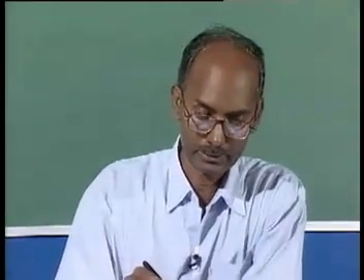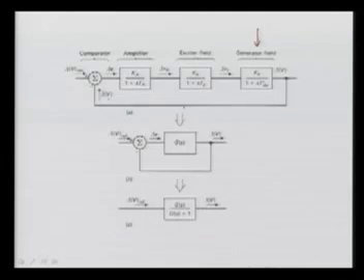So we can add the generator field effect, the field exciter modeling, the amplifier, and this is your comparator. The reference is coming from the voltage that is measured here, and that is compared with your VF, the reference value. This terminal voltage is going to be compared. So this is a closed loop with unity feedback.